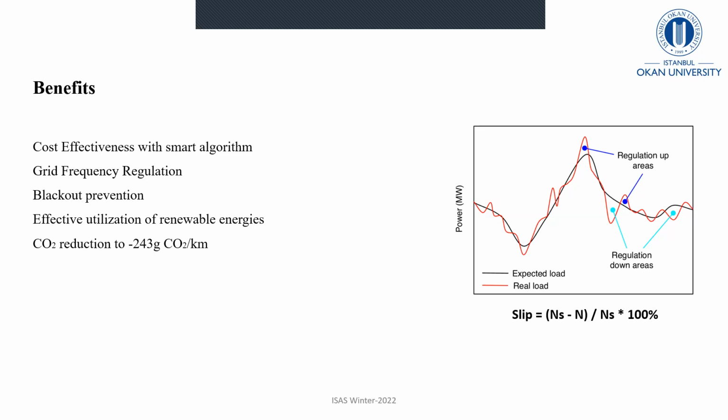for which the electricity providers and the governments are subsidizing and promoting these concepts: grid frequency regulation. That's the more technical part. What happens is, if the grid supply is higher than the consumption, there is a formula for the slip of a motor. There's a generator on the generation side. When the mechanical speed of that motor increases because of less load on it, the frequency goes up. The frequency has started going up.